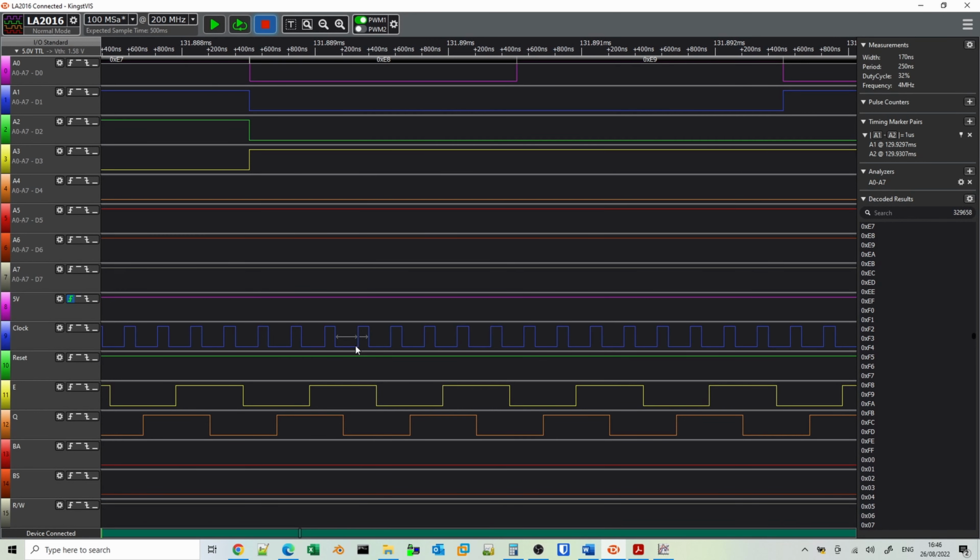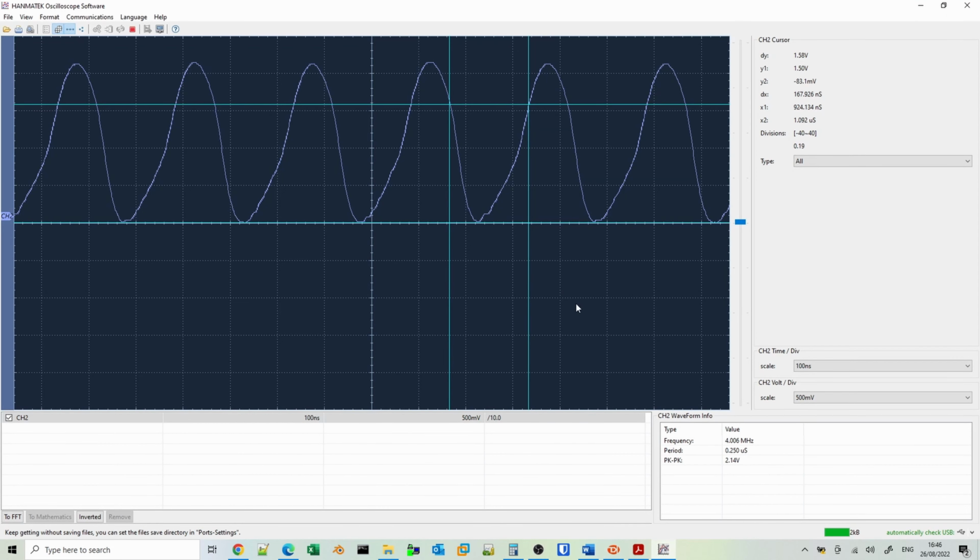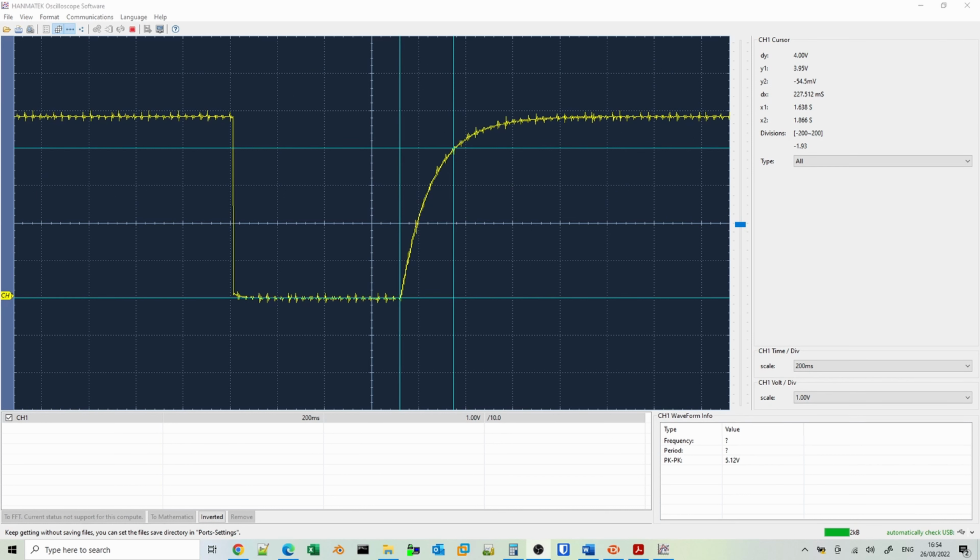So that really explains why the clock signal here, we're seeing this 34% duty cycle up in the top right hand side here, is because our logic analyzer is treating logic 1 as anything over 1.58 volts, and what this indicates here is that this is only occurring for this period of time. So that explains the reason why our clock signal is appearing with this duty cycle.